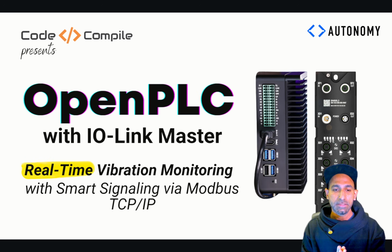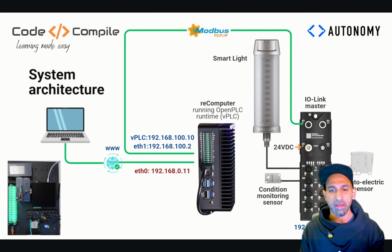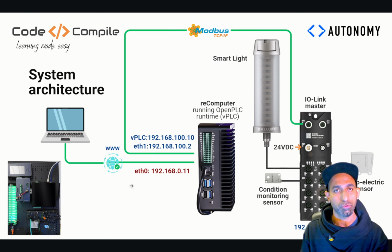All right. So let's understand the system architecture, how this has been connected. There you go. So now you can see that in the center, I have my reComputer running OpenPLC runtime. So the virtual PLC instance is already running here. And this is what I've explained in the last video. So if you notice here, you have two Ethernet ports on this edge device. One is Ethernet 0. This is connected to the web. So that's how I deploy my program. I will create the program in my web browser and I will deploy it directly to my edge device because the edge device has a connection to the internet via this port, right?